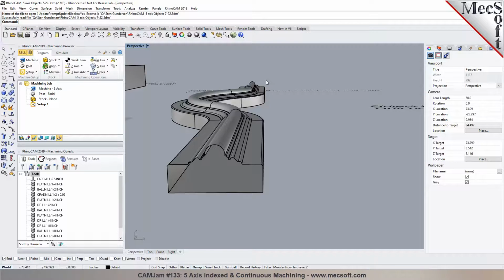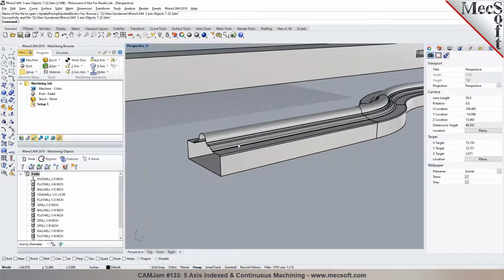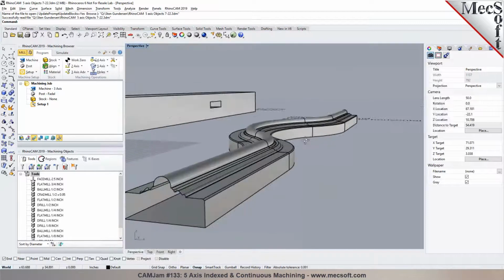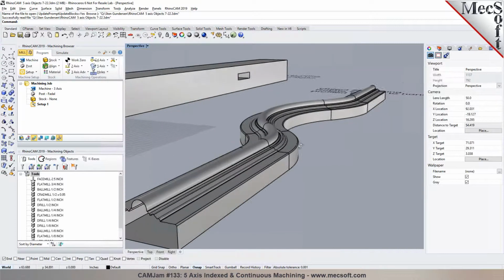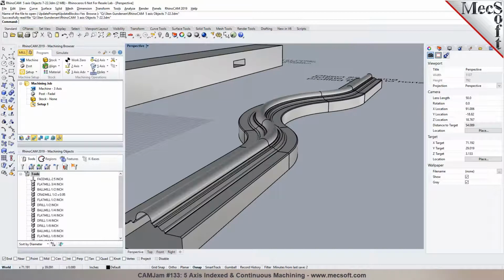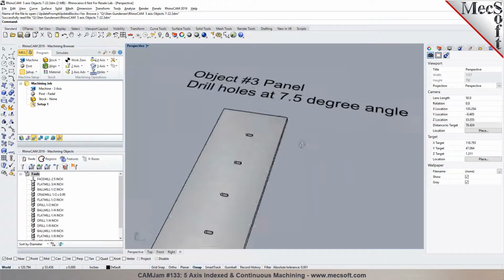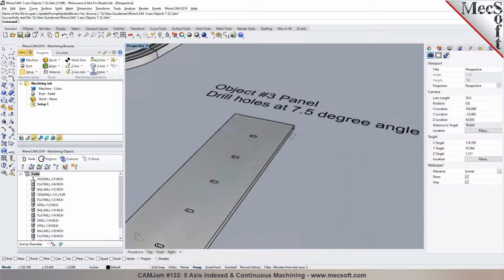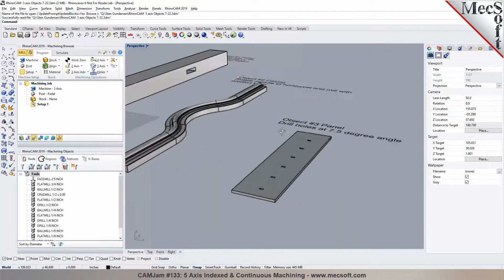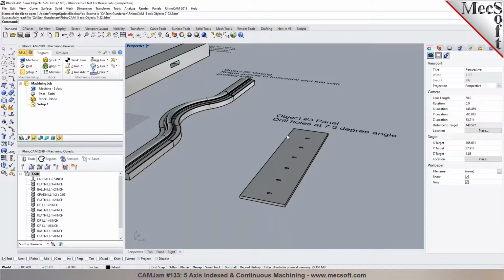Okay. So that would be a user-defined tool, and then you can do a two-axis operation, or an engraving operation, because form tools or user-defined tools are limited to two-axis operations, and maybe engraving operations. Well, yeah, and in fact, there really isn't any need to have that profile in place. I simply wanted to have the idea there. Essentially, the head needs to rotate to horizontal, and it needs to, as you say, follow a two-axis toolpath.